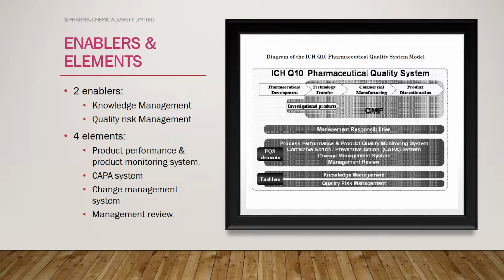So now, how you're going to communicate your investigations, how you are monitoring and your implementation of corrective actions and preventive actions. So that is non-conformance from both sides, because now, blowing out a rupture disk, you have two consequences. Depending what is inside of that reactor, you may have a very toxic gas. So the non-conformance is that you can kill somebody, or you can exceed the occupational exposure limit. If you have a respirator with two cartridges, you're going to exceed the concentration that those cartridges can handle, and then that toxic gas can go through the mask for sure.